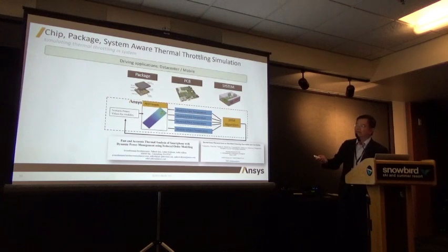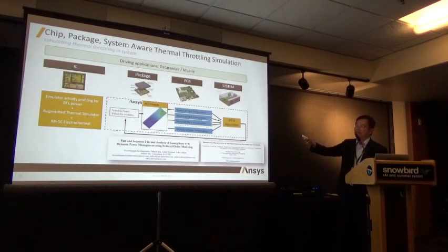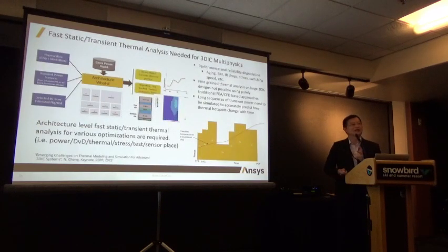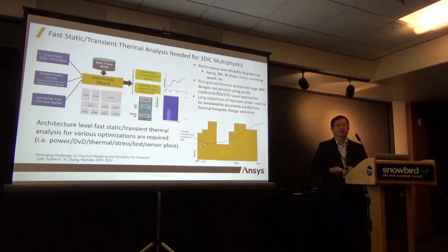This is the traditional solution: building reduced order models, working with Qualcomm and Samsung, and applying IcePack in combination with a very coarse grid on chip, we can build a dynamic thermal management system. But the need now is for fine-grained thermal simulation on chip.